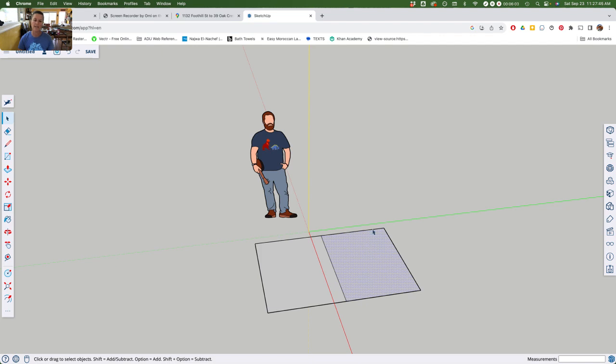Whenever I can click on something and highlight it, that means that it's what's called raw geometry. Now, the reason why that's important is because raw geometry sticks to itself. The most important thing in SketchUp is to not ever leave raw geometry. And so I will be always grouping or ungrouping things to make individual things as opposed to this raw geometry.